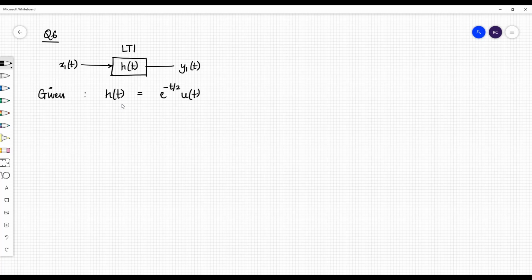You also already know that to find the output of any LTI system, all you've got to do is find the convolution of the input with its impulse response, right? And doing convolution graphically is always very easy, and it helps you avoid mistakes if you draw the flipped and shifted version correctly.